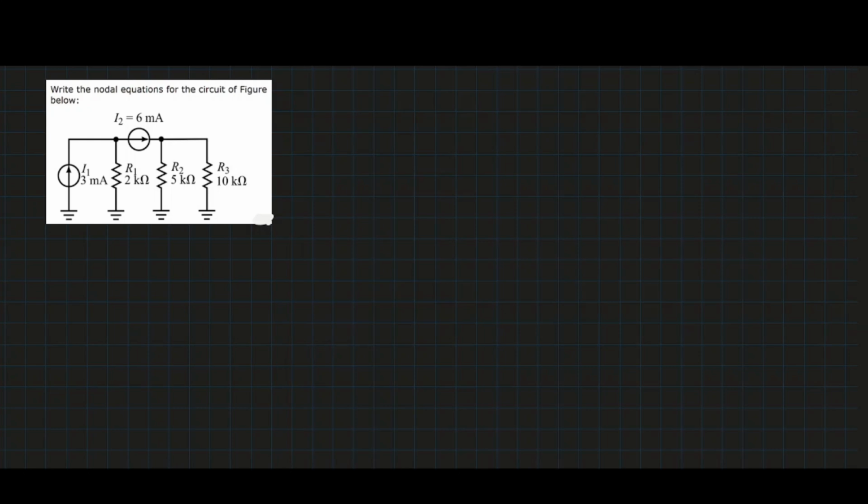Hi guys, so we're supposed to write another equation for this circuit. Now, do not be alarmed. This is saying ground. All of them are ground. Which means you can literally connect all of this with a line and every single voltage at this point is zero. It's just like a normal circuit.